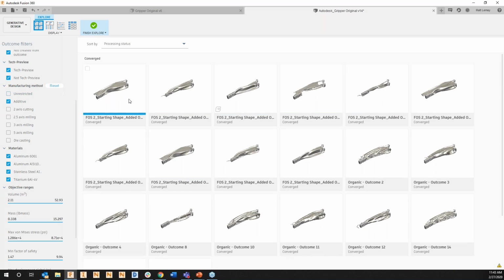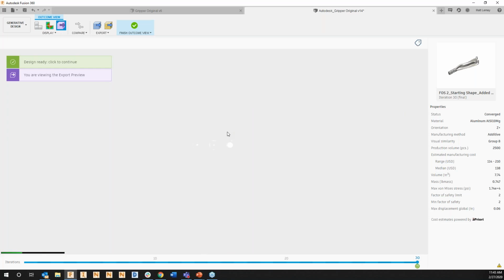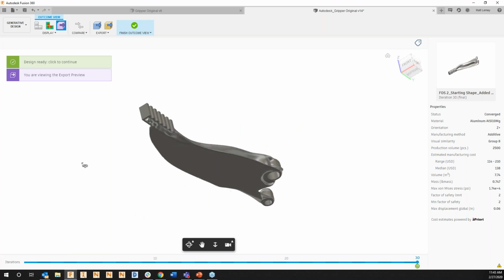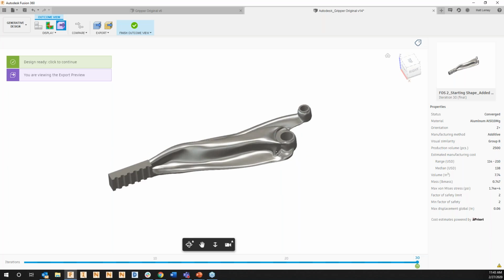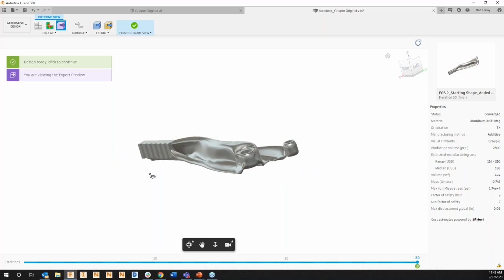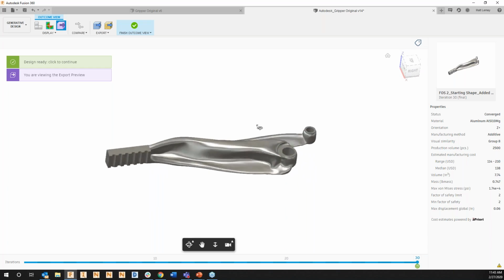Next, we have our more traditionally additive manufacturing constrained parts. So if we click down on one of these, you can see this is a part that's meant to be self-supporting in the positive Z orientation. So if our platform is here, everything is self-supporting vertically from that, from the overhang and from the minimum feature size that we set.